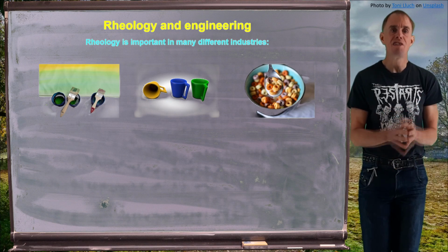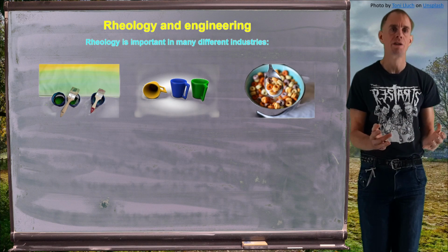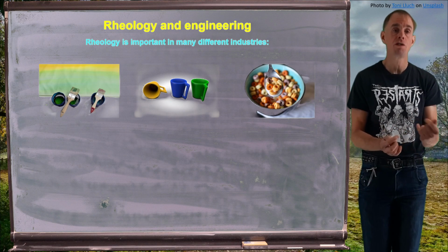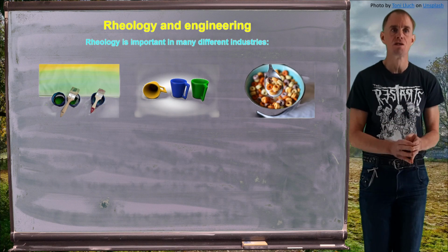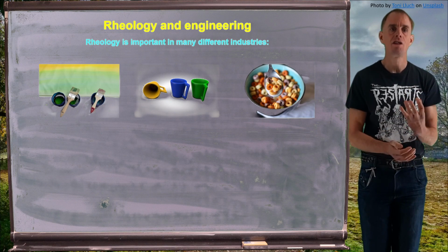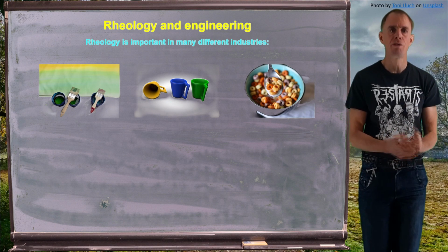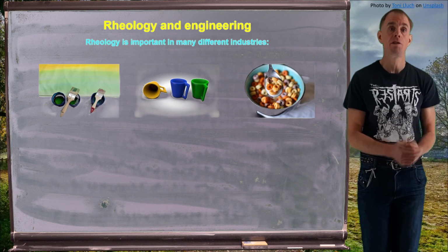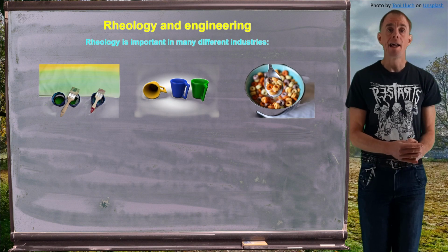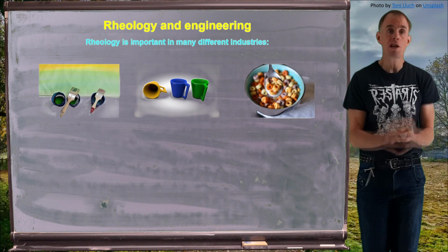So the science and engineering behind extrusion is an absolutely fascinating one, and one that you'll probably see in a polymer processing course, but understanding how the fluid behaves in an extruder is very much the science of rheology. Because if we look at how fluids flow and deform through that extrusion line, the stresses they're subjected to and the stresses that they may store if they're viscoelastic in nature, the whole goal of the extrusion line is to shape form.